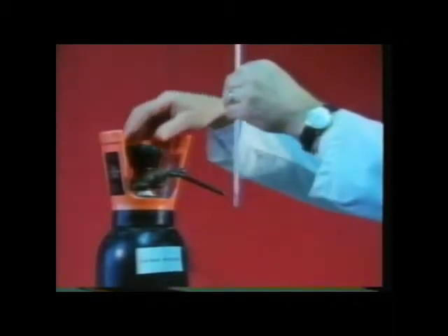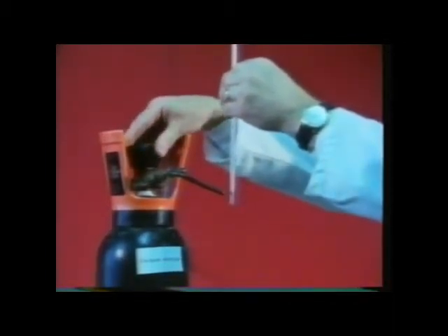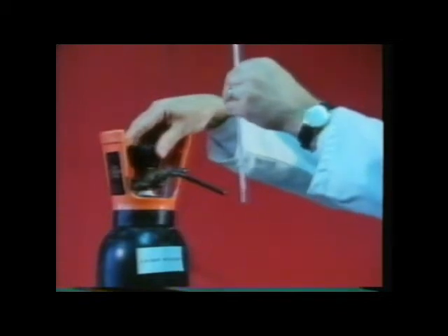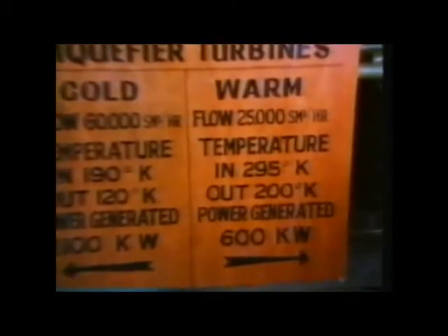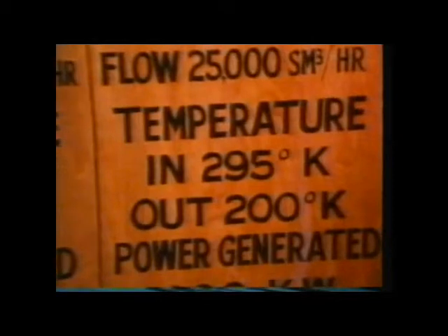But if you take a compressed gas and release the pressure, let it expand, it loses heat. It gets colder. This effect is used to cool the compressed air so much that it turns into a liquid. The compressed air is allowed to expand in 2 stages.